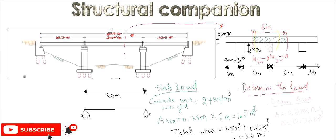Hinge support, roller support, and here we have our UDL, the one we have to determine. This UDL here, because we know it is distributed, is the load coming from this slab and beam. Here we need to apply it on this beam. This beam is continuous, so it is representing this beam here.